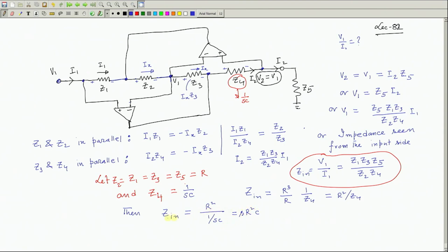Now, the impedance seen from the supply is s times something, s times L equivalent, because for inductance only the impedance seen is sL, and for capacitance 1 over omega C. Similarly, if Z4 is an inductor, this reciprocal business will make it a capacitance, and so on.